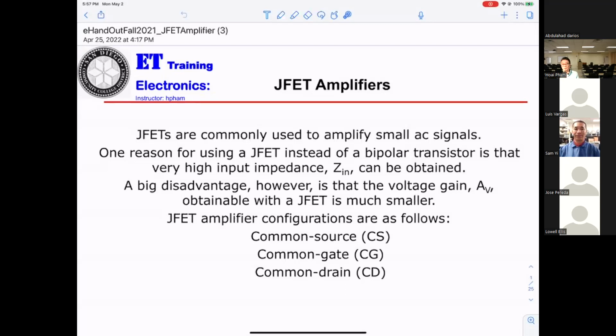You can see going down, they tell you normally what voltage is applied to the input of the JFET amplifier. So it can amplify lower than 1K, or 1 hertz? No, that's not talking about frequency. We're talking about the amplitude, the voltage. Frequency, I believe, is no problem. So it's not necessarily used for noise on the line amplification.